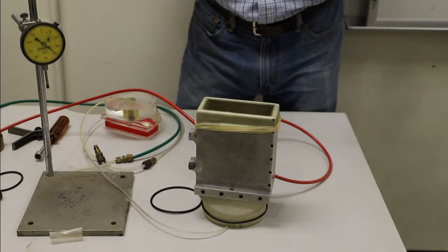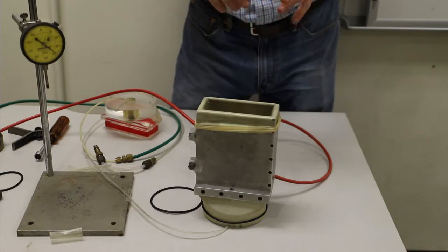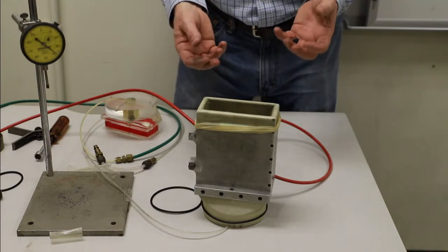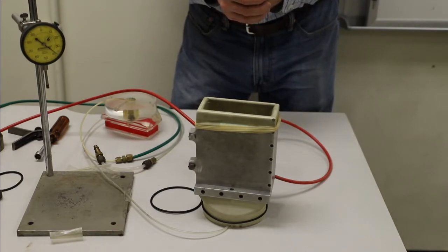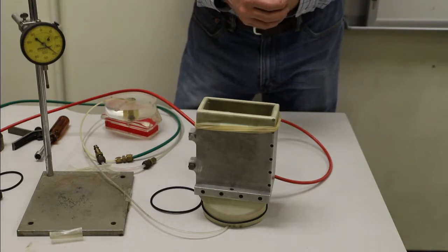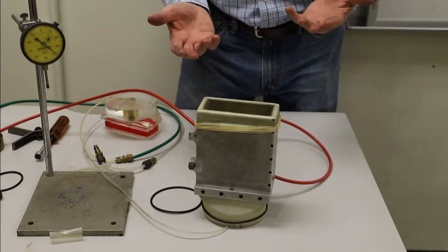So with the triaxial sample, we very carefully put the mesh with the cylinder at the bottom. We wanted to impart as little energy as we could while we built the specimen. And so if you want the opposite, if you want a very dense specimen, as you might guess, you want to impart a lot of energy.